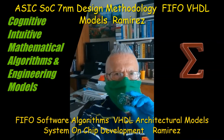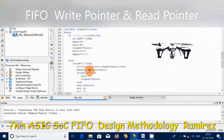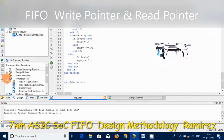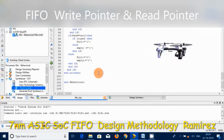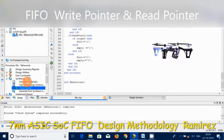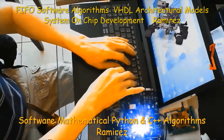Here I generate the FIFO pointers, first in, first out. So when reset is asserted, both read and write pointers are set to 0. The FIFO empty flag is asserted and the read pointer points to the valid data.